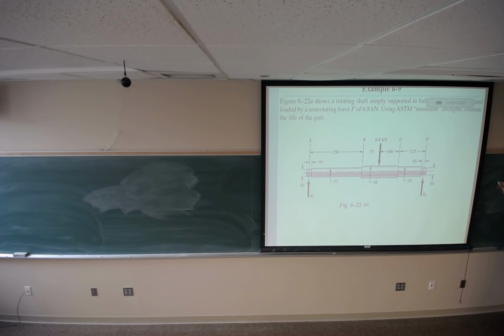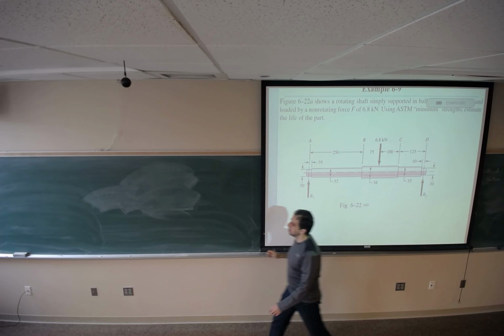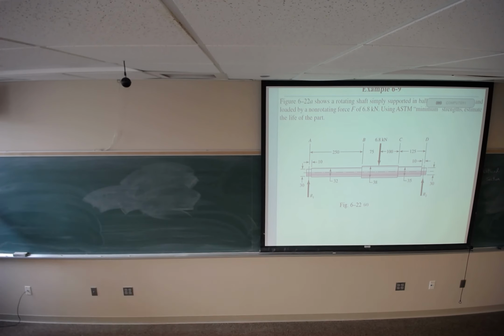First, what we did, we tried to find the critical section. There were 3 candidates for the critical section. Section E with the maximum bending moment.